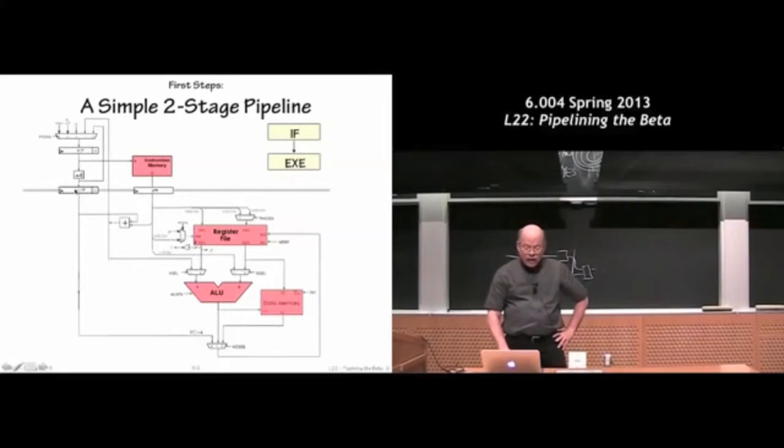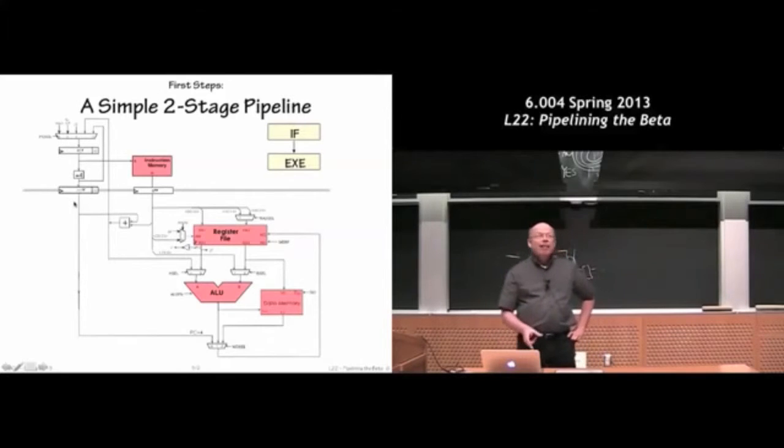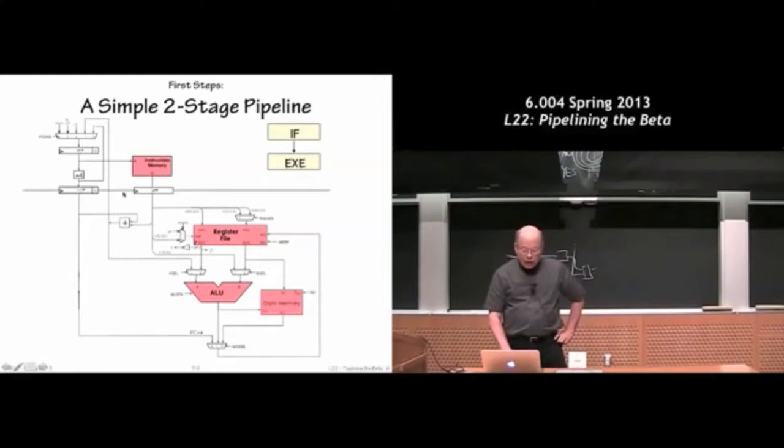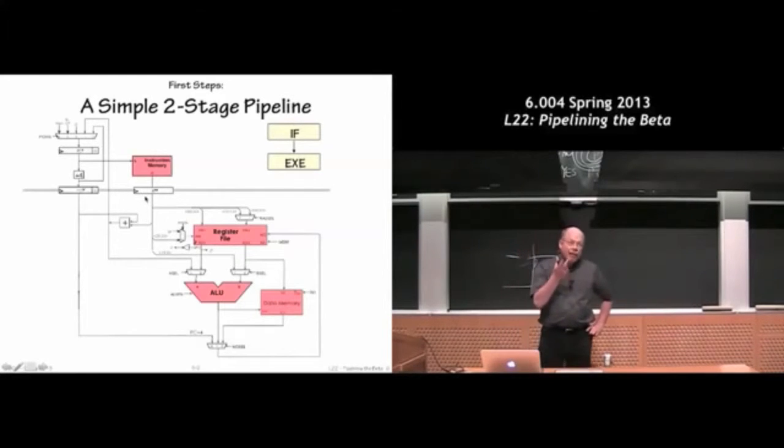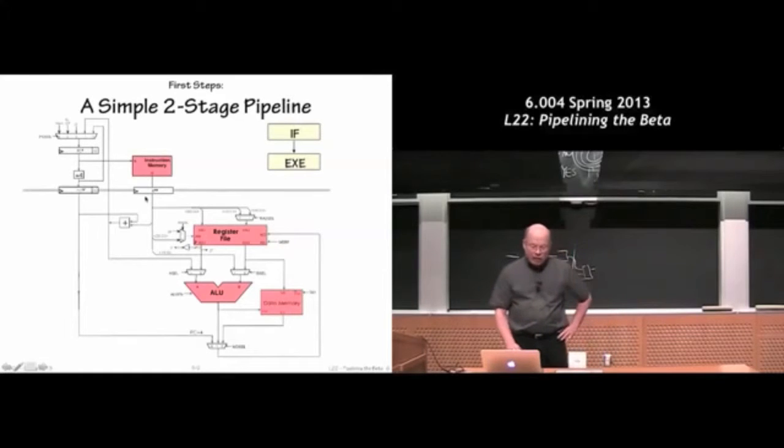And you look at this and say, fine, so to execute the instruction properly, I'm going to have its PC plus 4, because that's used by various instructions. LDR, or if I'm doing a branch, that PC plus 4 will need to be stored in the register file. So I'm going to need that piece of information, and I'm certainly going to need the 32-bit representation of the instruction itself. I can hardly execute the instruction without the binary representation. And so those are the registers we add here. And in general, one of the things we'll be doing as we do pipelining is adding more and more registers.